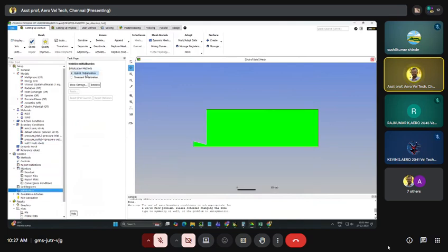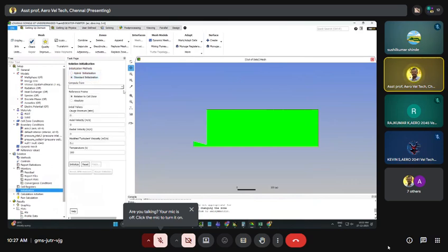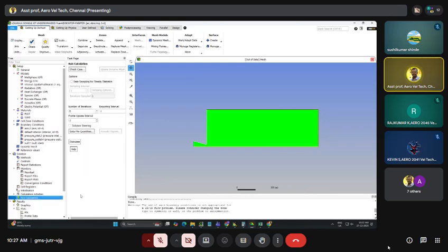So initialize the solution, go to default, it will be hybrid, select standard, and then give pressure inlet. You will get some velocity around 400. That is fine. Initialize. So initialize, done. So run calculation, finally give run calculation. So just number of iterations, you just add some number of iterations. Say first initially I'm giving 10,000 iterations. Okay. So we will see, you give calculate.